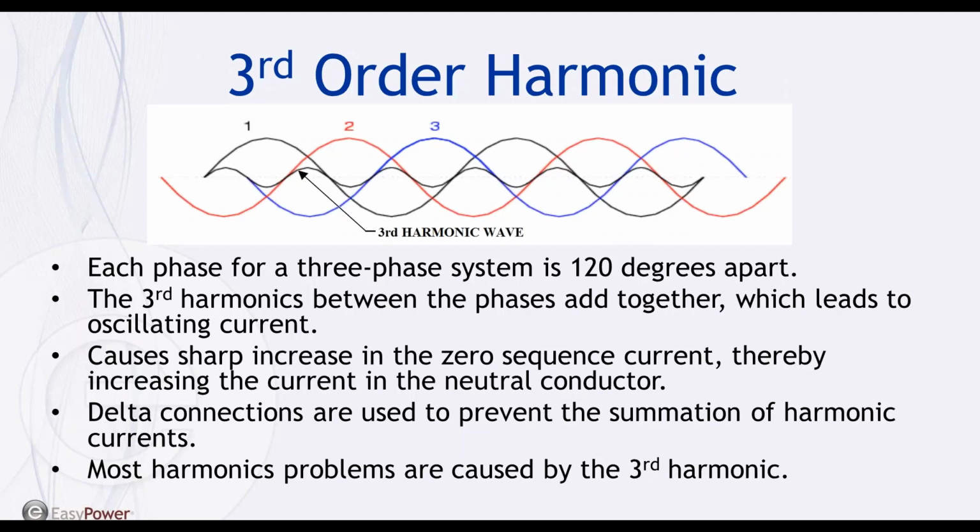First, it is because motors and/or generators that use three-phase power are more efficient due to the constant torque the phases supply. Second, it is because after power is supplied to the load, the three phases can theoretically be added onto the neutral wire and cancel each other out. This saves the utility company from creating return wiring to the power plant.